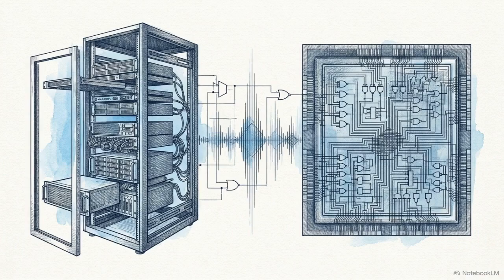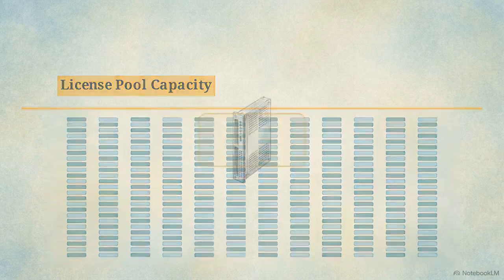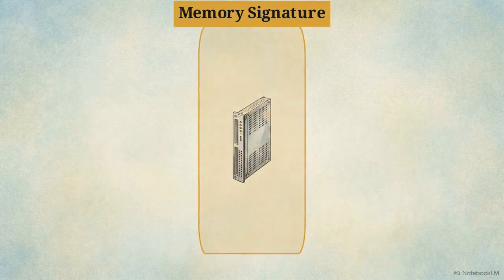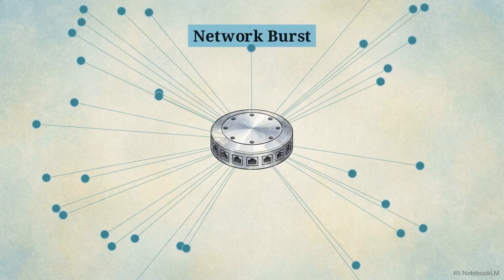Electronic design automation is not a single uniform workload. Every stage of the pipeline presents a distinctly different demand profile, known as a resource signature. Consider RTL regression testing. Its signature is fleet computing, thousands of test jobs gated by your software license pool. Contrast that with physical design, requiring massive single-node memory. Finally, physical verification, like DRC and LVS, creates severe network congestion.